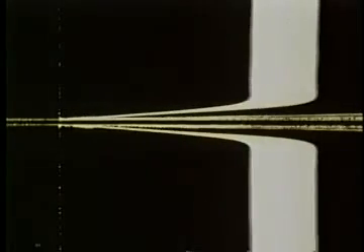We have seen the behavior of two-dimensional boundary layers on a flat plate in a uniform velocity field. So far, the pressure gradients in the flow direction have been negligibly small. However, in most flow situations, there are regions of decreasing pressure and regions of increasing pressure in the flow direction. We will examine these two flow situations separately.